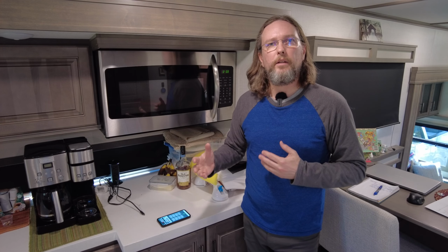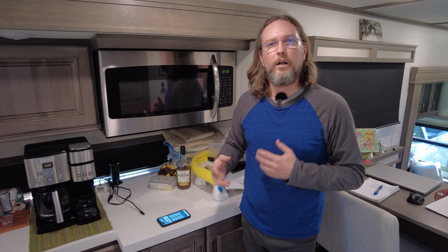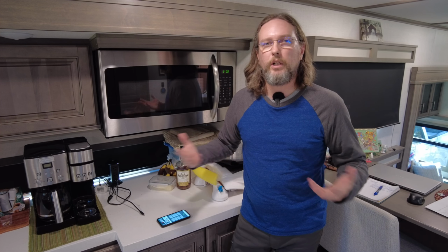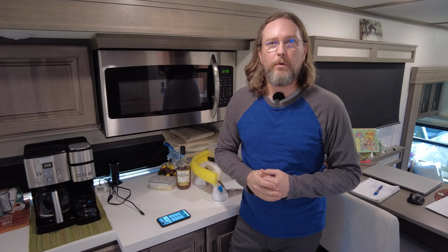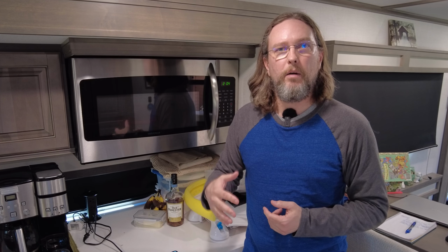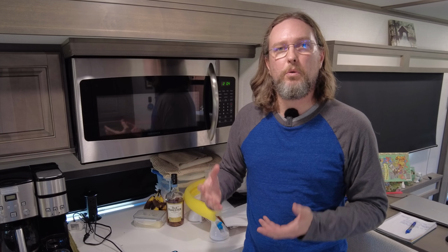So now let's take a look at the second technique of performing this power audit. And I really think this is the easiest way to do it. I've kind of coined this term as the total power technique, because in this technique, basically what we're going to do is a mock trial run of boondocking for a 24-hour period. While we're doing that, we're going to constantly monitor our power via our app on our phone from that surge protector. Then when it's complete, we're simply going to capture that number, which is going to tell us exactly how much power we used over an entire 24-hour period.